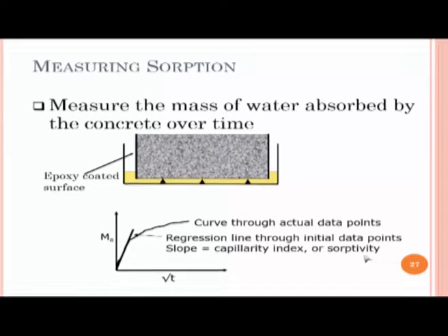Okay. So again, this is a typical test that is done for bricks also. Remember, for bricks what you do, you place it in water, and that water basically gets capillary absorbed into the brick and comes out with any salts that are there in the brick, and you can actually study efflorescence with that test method. That is the efflorescence test method.